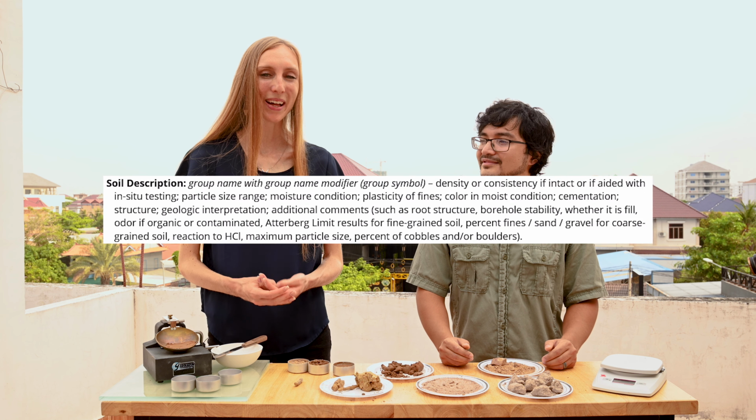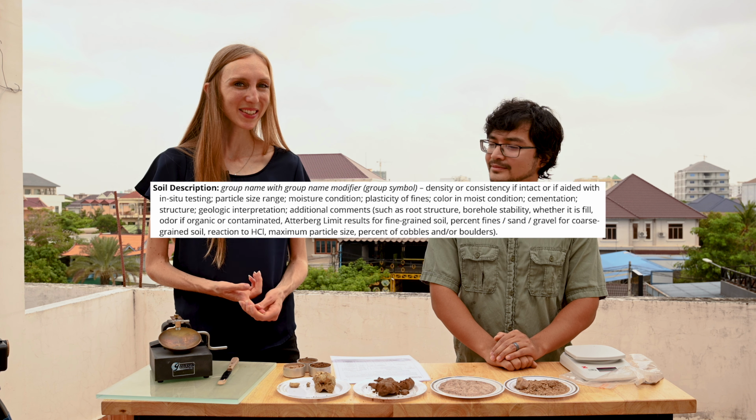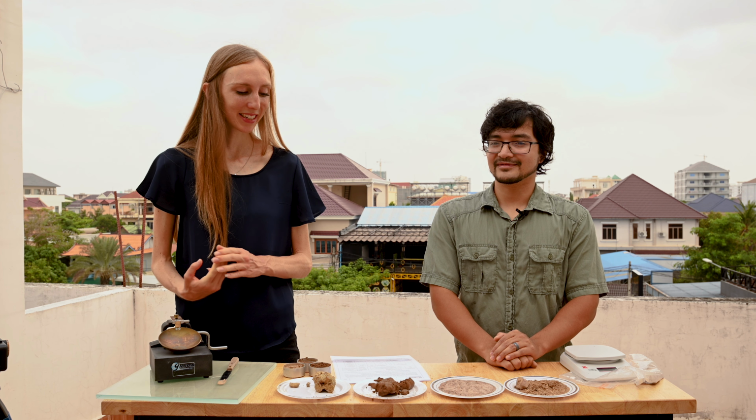Once you have performed a visual inspection and determined the soil type, combine all of your observations into a concise soil description. The boring log legend that we mentioned at the beginning will help walk you through this process. Combine all of your observations, color, moisture, particle size, into a soil description to easily characterize your soil.